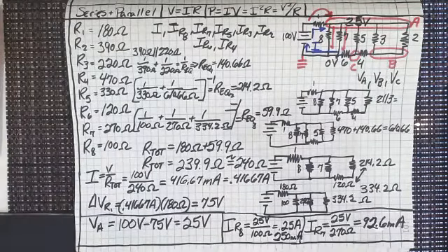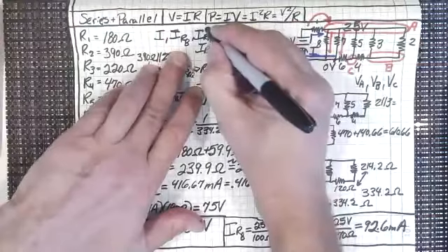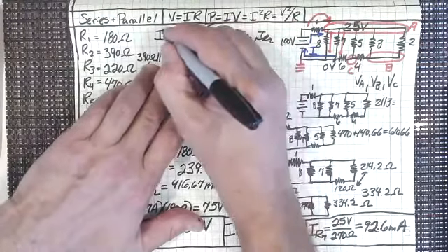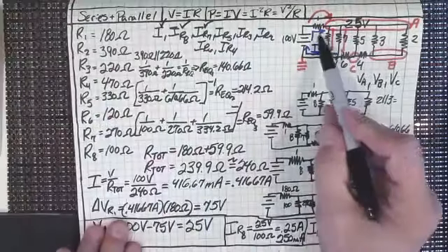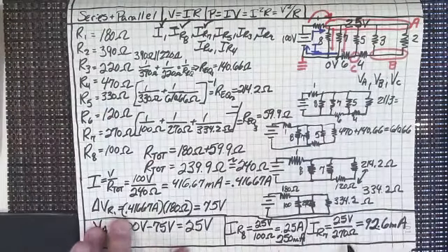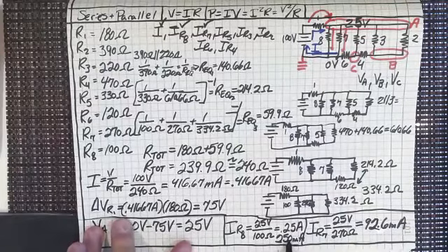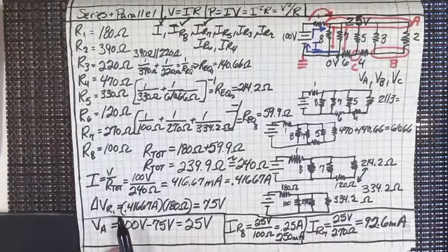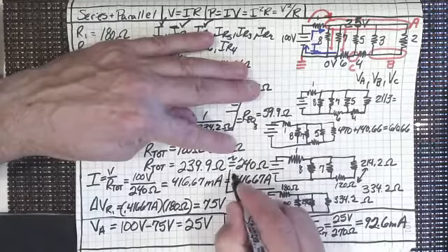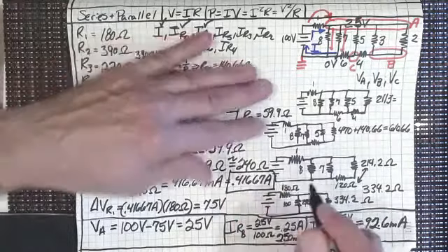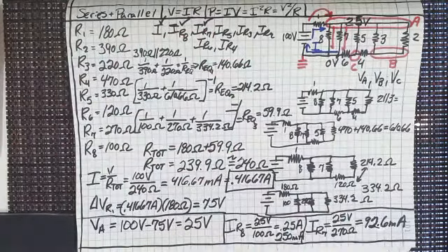So let's look at what we've got now. Now we've got I R sub 7 done, I R sub 8, I R sub 1. That's really because that's the I that's flowing in through I R sub 1. And so we know what these are now. And we know what the total current is that's flowing out of the power supply. So can't we use Kirchhoff's current law?